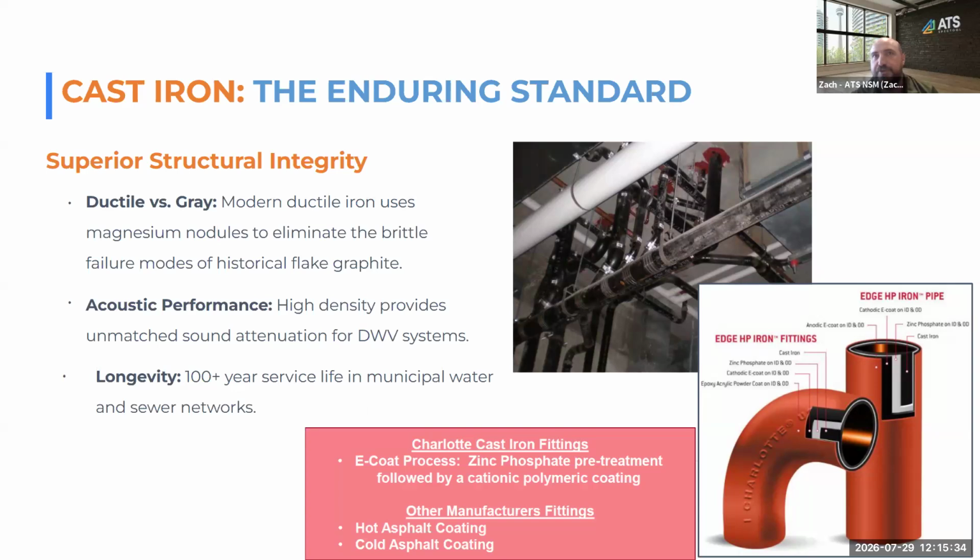And obviously, you don't need to do the entire piping assembly with this coated product, but from your waterless urinal or from your ultra low flow washroom to the stack, that leader is a great use case for this E-coated product. So that's one of the many reasons that we recommend these for applications like your commercial kitchens, your underground parking garages, or these ultra low flow applications.